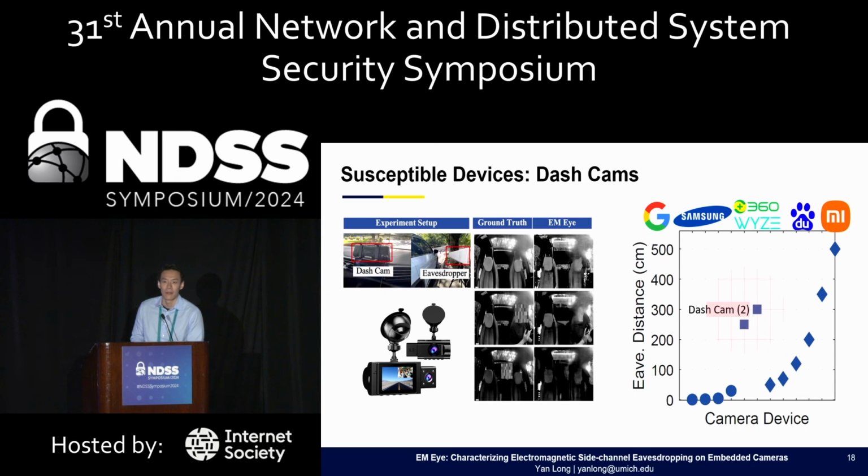Yeah, jamming plus. I think if we're looking at an external device that emits some jamming or replacement signal, it's actually very difficult because the signal is basically everywhere. It's a baseband signal, not a carrier signal focused on a specific frequency, so it spans a very large frequency band. A jamming device would have to be very expensive to cover such a large frequency band.